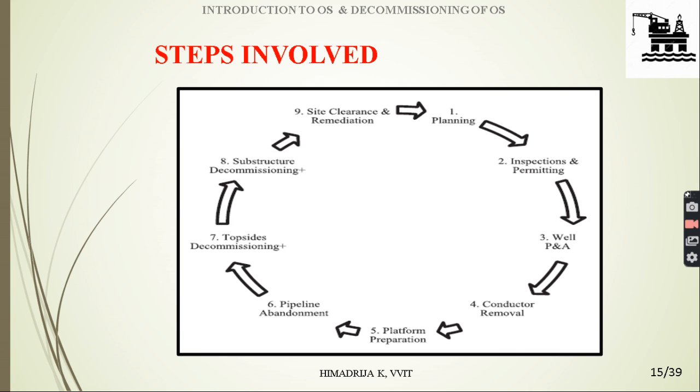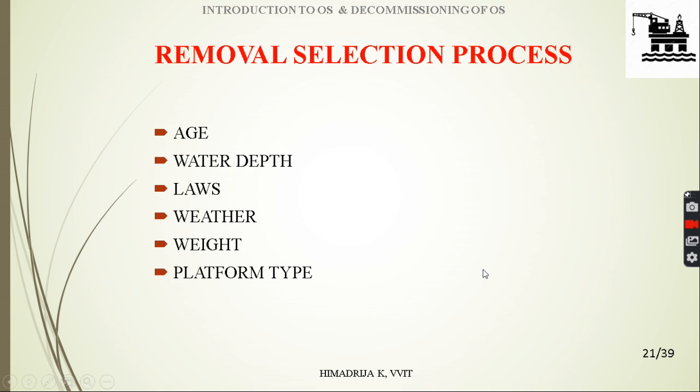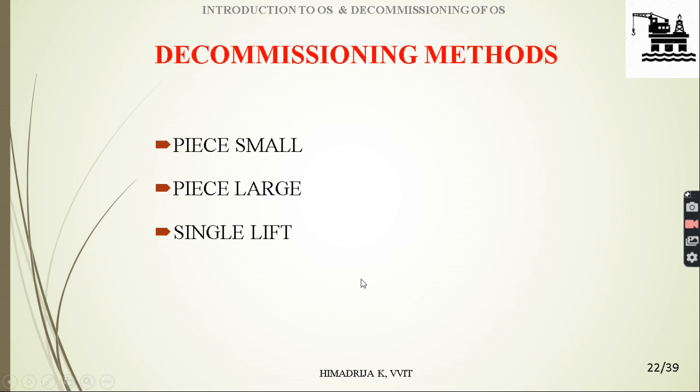And it can be decommissioned in a stepwise manner, with topside decommissioning first, and after that the substructure is decommissioned, and then comes the site clearance. So the removal selection process depends upon the age of the offshore structure, the water depth involved, the laws and regulations, the weather or ocean environment, the weight of the structure, and which type of platform it is, whether fixed or mobile.